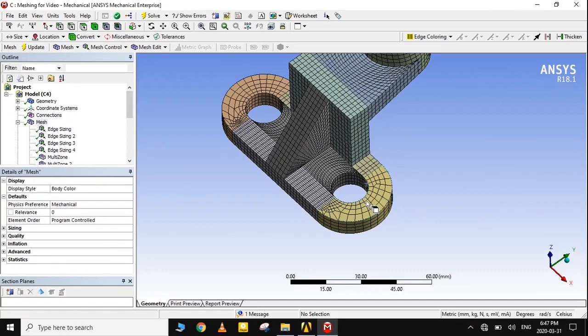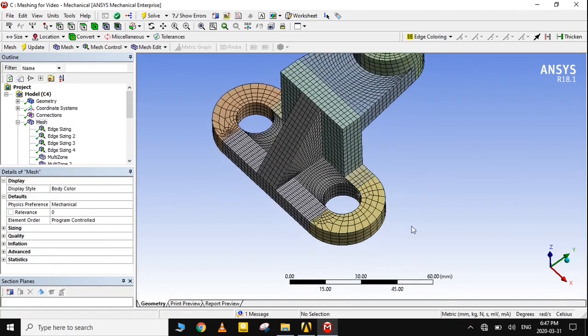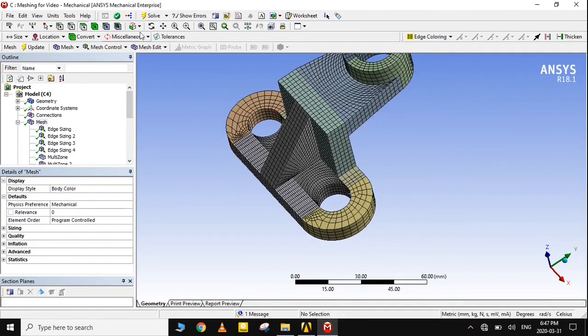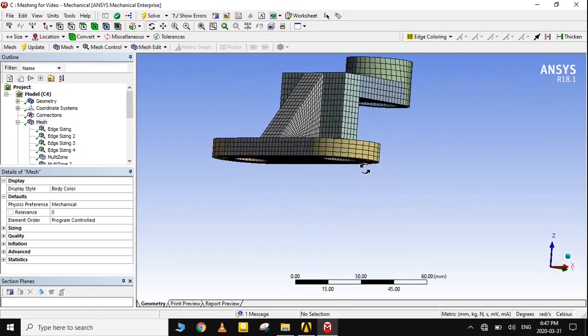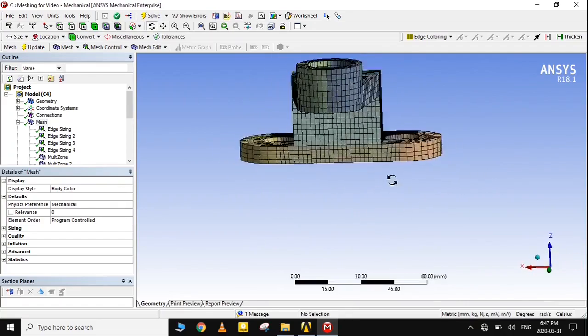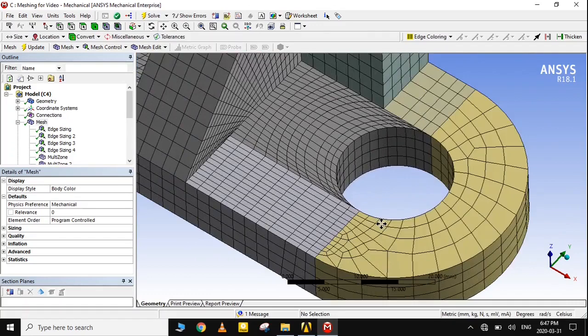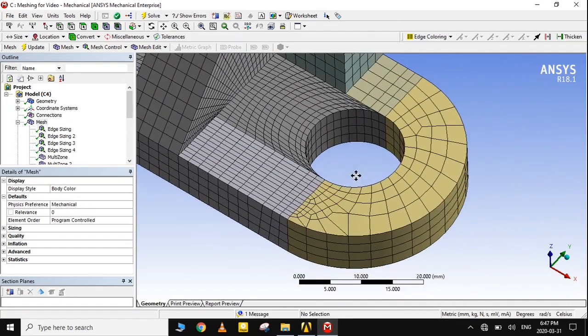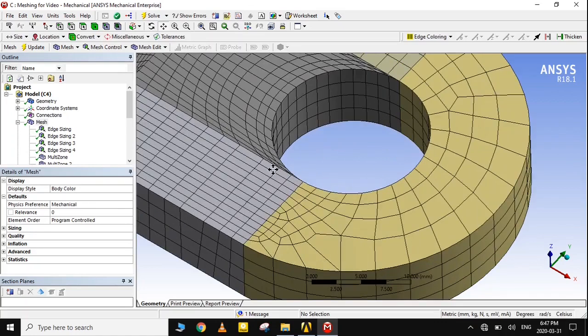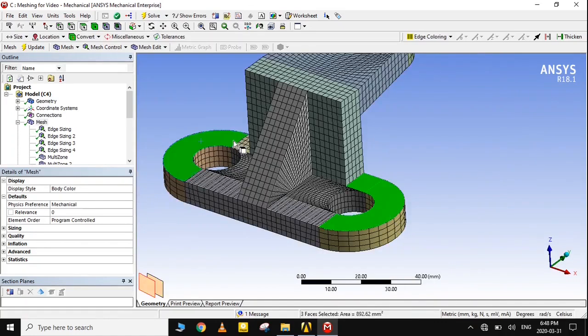Hexahedral mesh is formed. Though it is not structured at some areas, it is still acceptable. The reason why it is still unstructured at some part is that it has different number of elements on either side, because of which it has to make a transition between unequal number of elements. We can structure it by increasing the number of elements on the other side. For it, we must go back to the body from which this family of lines originated. It is the rectangular box in the middle.